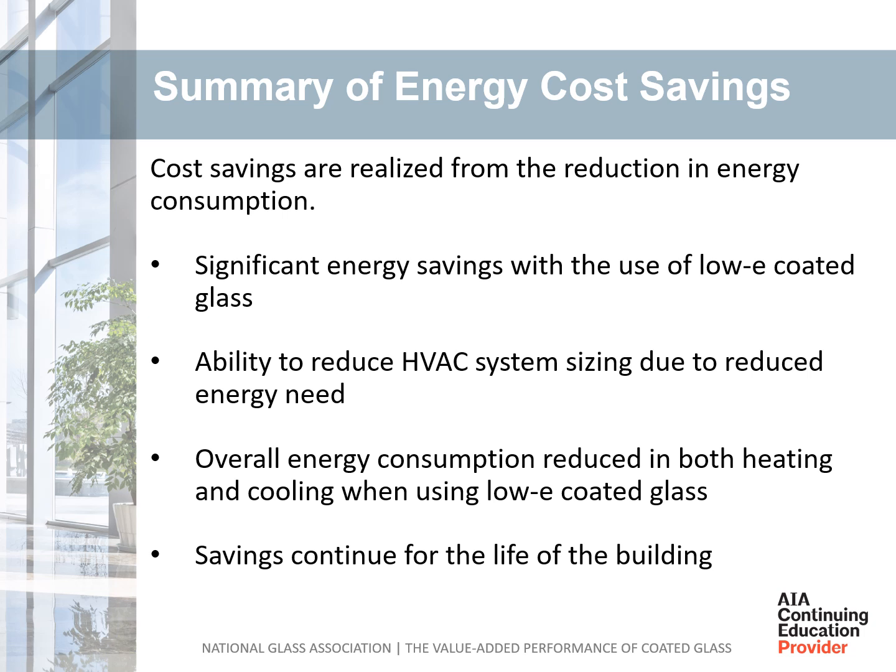In summary, cost savings are realized from the reduction in energy consumption. There are significant energy savings with the use of low-E coated glass. There is an ability to reduce HVAC system sizing due to reduced energy need. Overall energy consumption is reduced in both heating and cooling when using low-E coated glass, and savings will continue for the life of the building.